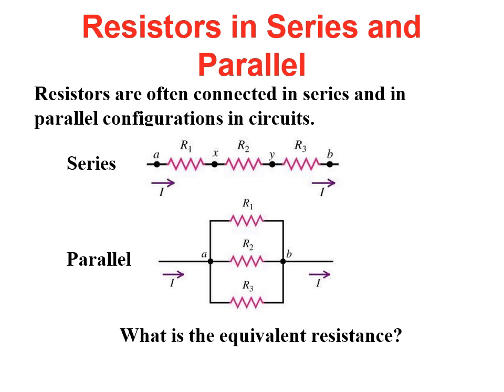If a current is applied to these three resistors and comes through from point A, it will split into three. Some of the current will go to R1, some goes to R2, and the last part goes to R3, and then they join together again at point B. When you have series or parallel resistors, you always have to calculate the equivalent resistance of the parallel or series resistors. It gives you the total equivalent resistance of the circuit.